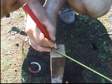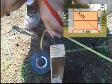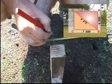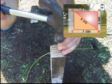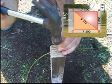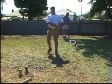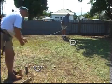The second diagonal BD measurement and the side AD measurement intersect to locate the fourth corner of the building. Measurement of the closing side, CD, is made to check the accuracy of the set-out.